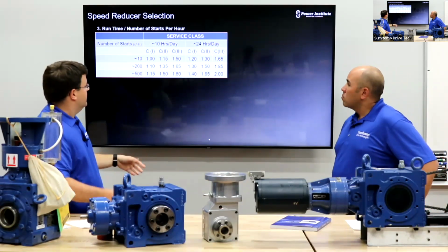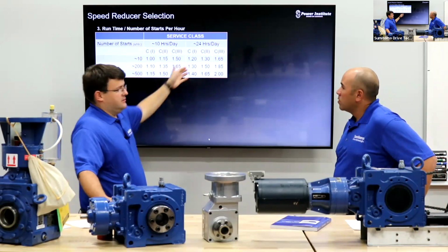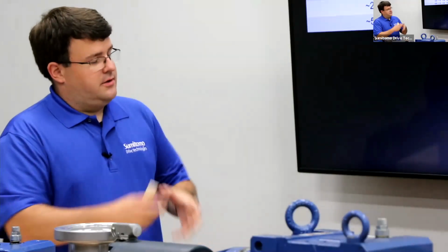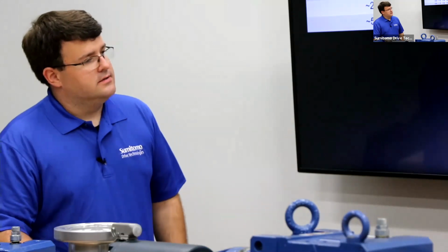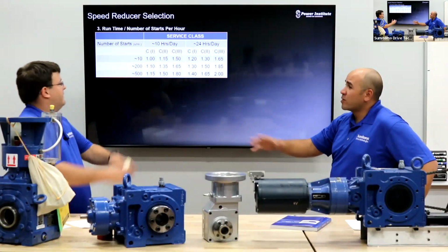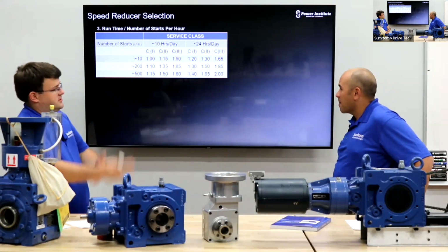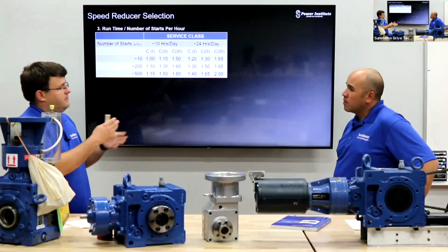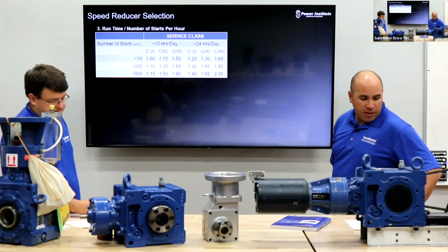So it would get larger. That's where it's an additional service factor. So we'd start multiplying service factors to get it to a higher selection. A beefier selection would be the easiest way to describe it. Gotcha. So this is a supplemental above and beyond. Correct. So you have the AGMA reference one, and then it's just a supplemental one on top of what we've already established. Okay.